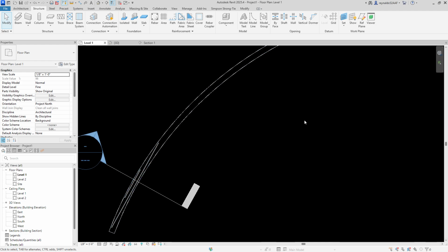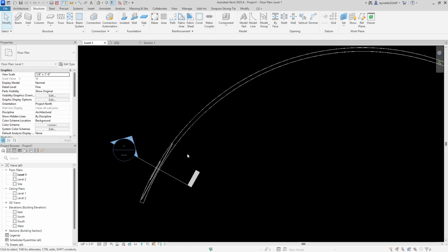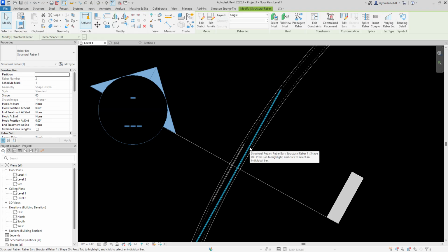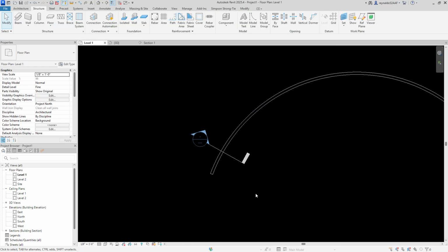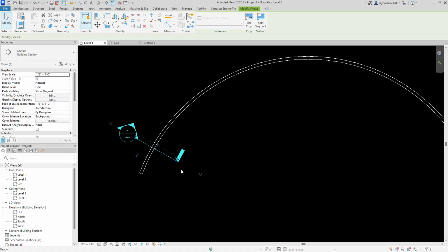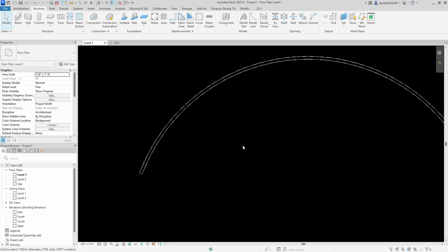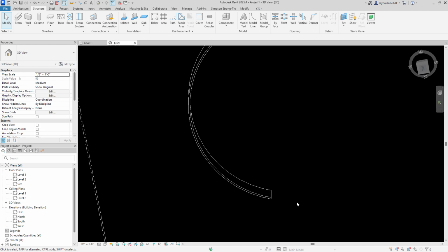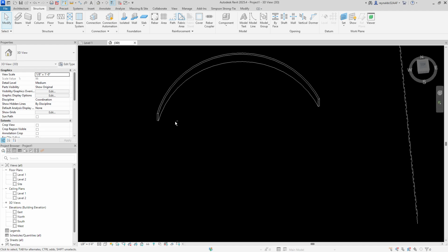And I wanted to show you the wrong way to go about doing this. That way, first of all, it's a refresher from how to place rebar when you have a straight wall. And secondly, so that you don't go about placing it the same method on a curved wall. So I'm going to delete these two. And whenever you're dealing with a curvature wall, you're not going to need to do a cut. And most of the time when you place the rebar, you will want to be in a 3D view, just like this, when placing a rebar.